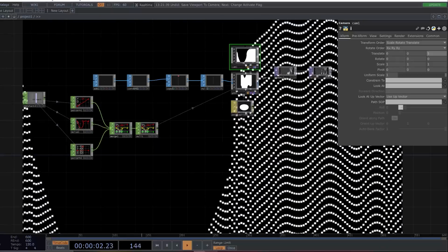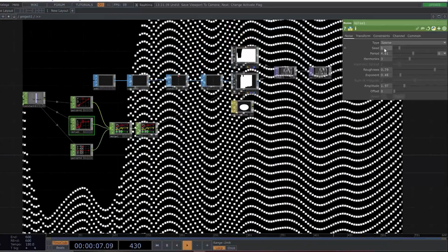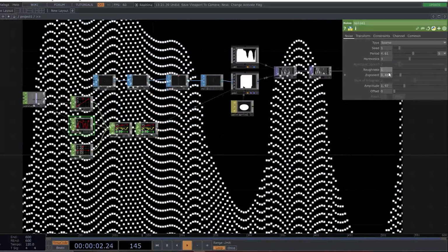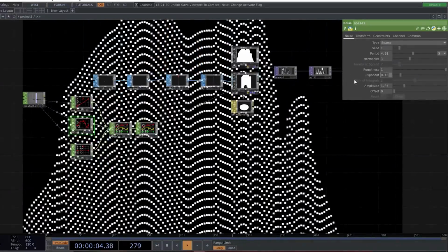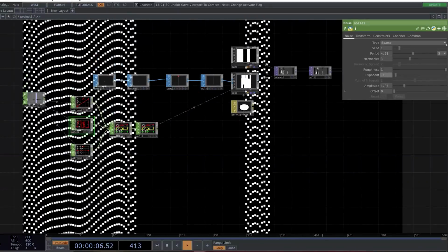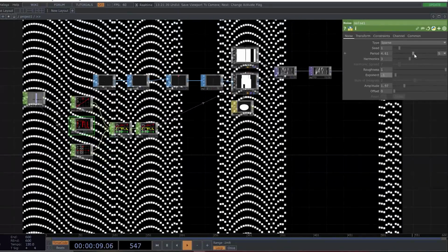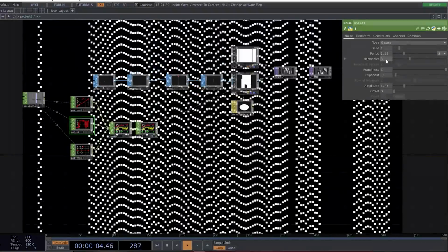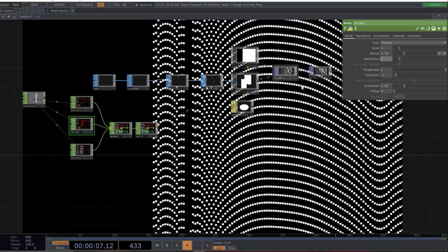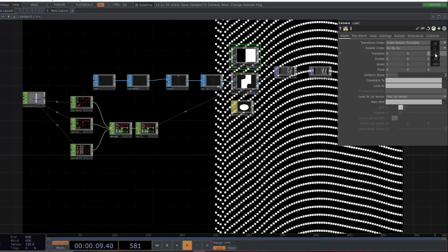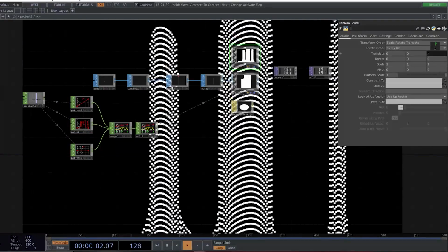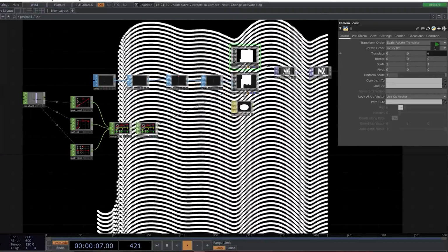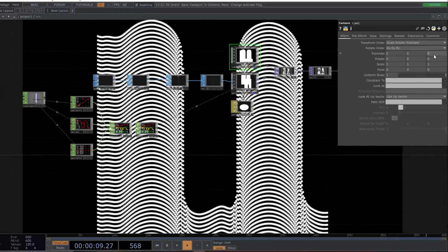All right, so the values that we're going to put: we'll make roughness 1, we'll have exponent value as 0.1, we'll have period, which is this, and we'll make harmonics 1. Let's go and, yep, there you go. So this is how my new pattern's coming up.